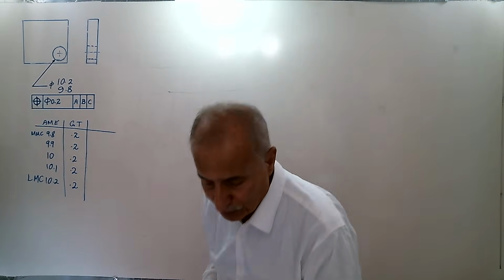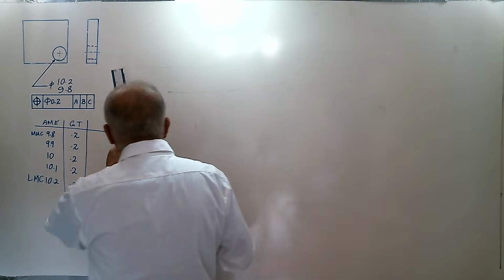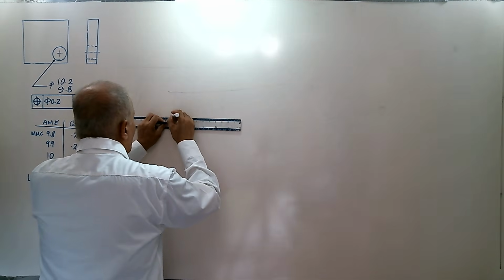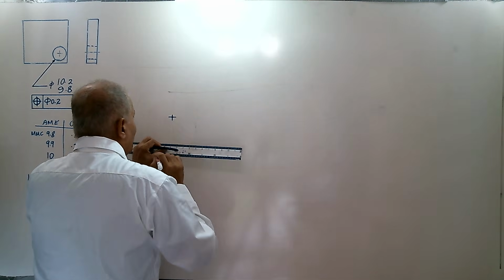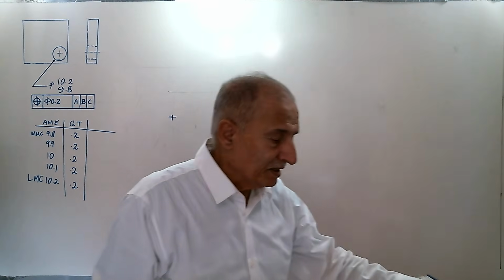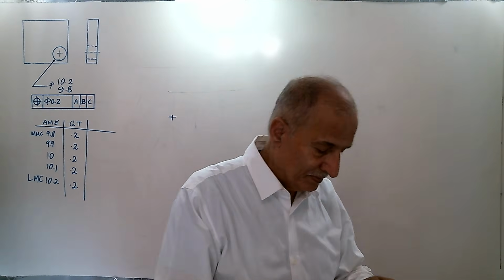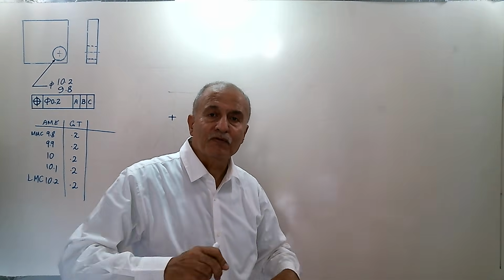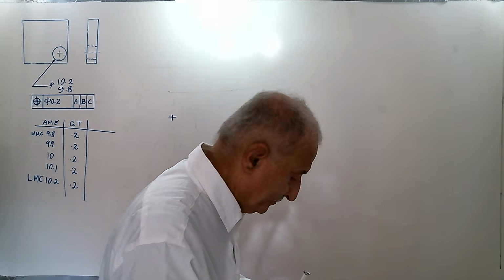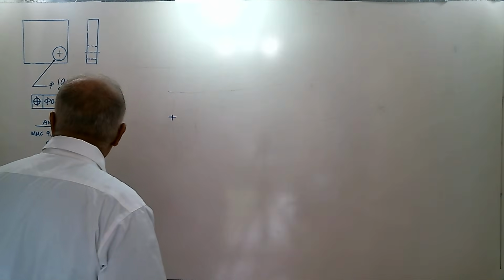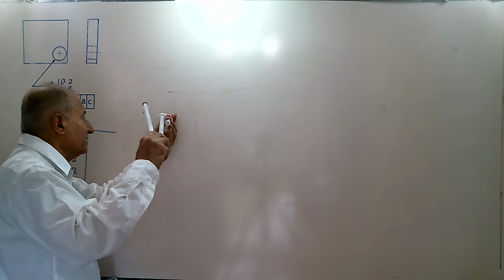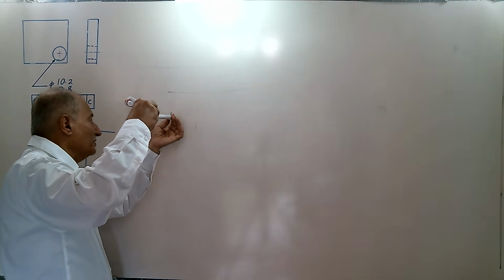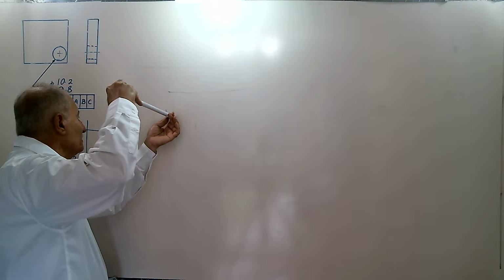Let's consider the position, for example, here. This is the true position of the axis of the hole. And we draw a circle which is equal to 9.8. Ideal case. We consider the ideal case here. Then we talk about its position tolerance.